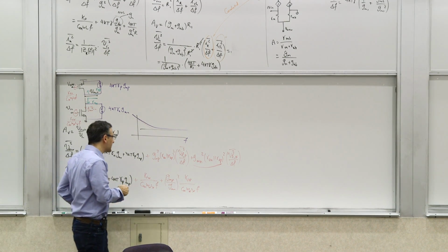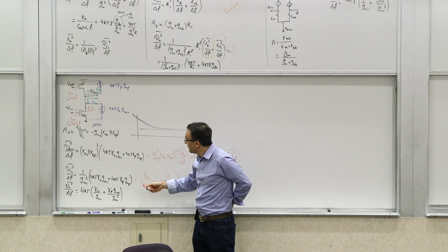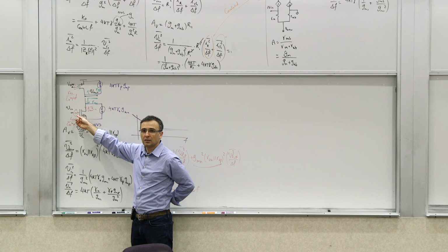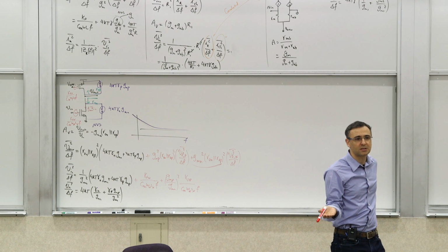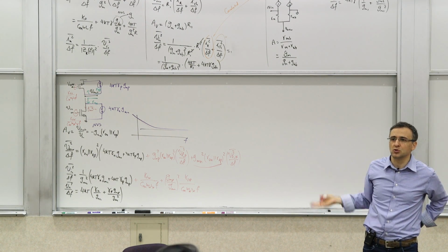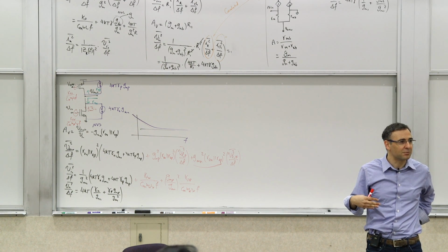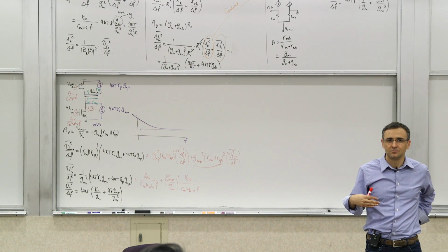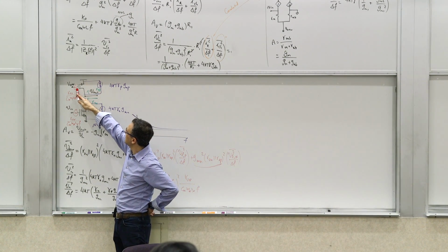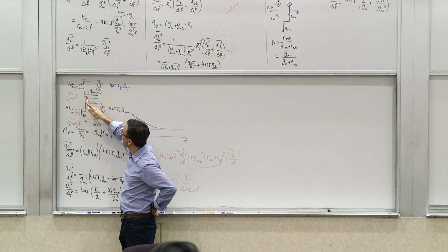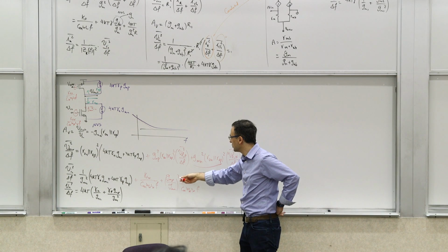So now the other thing that you see is that the flicker noise of this guy is just directly there, which kind of makes sense. I mean, you could have said that from the beginning, right? That's where the noise source is. We didn't really need to take it to the output and bring it back to the same place, right? Now, this guy, being at a different place, goes through the GMP of this guy and then gets divided by GMN of this guy. And that's why you get the ratio.